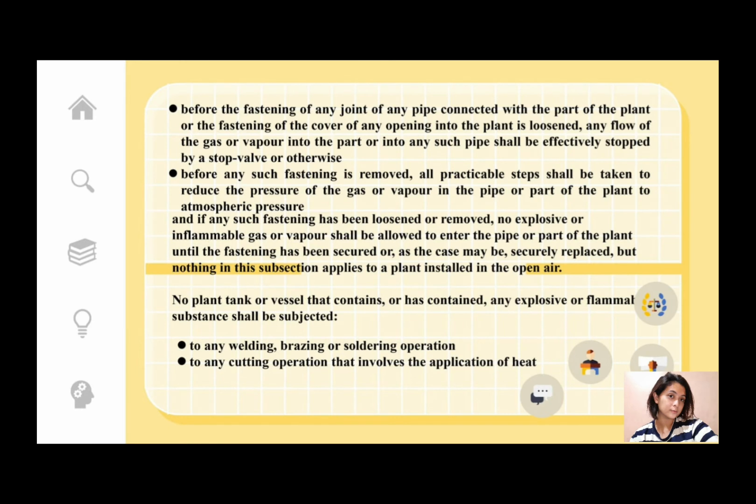So Section 31, precautions with respect to explosive or flammable dust, gas, vapor, or substance. Where, in connection with any grinding, sieving, or other process giving rise to dust, there may escape dust of such character and to such an extent as to be liable to explode on ignition, all practicable steps shall be taken to prevent such an explosion by enclosure of the plant used in the process, and by removal or prevention of accumulation of dust that may escape in spite of the enclosure, and by exclusion or effective enclosure of possible sources of ignition.